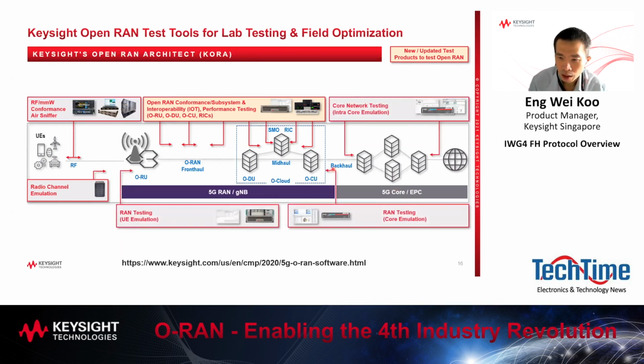And for testing the ORAN as a system under test in end-to-end system testing, we have our RAN testing UE emulation framework that is capable of emulating thousands of UEs and lots of cells, so that we can stress test the ORU, ODU, and OCU together and the rigs, and then the core emulation to make sure that the RAN can be tested in isolation.